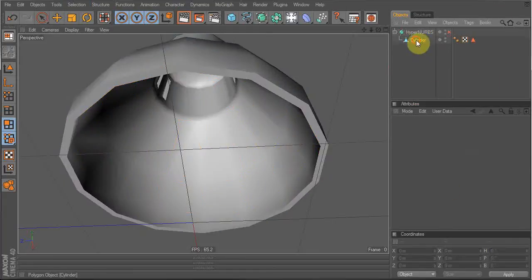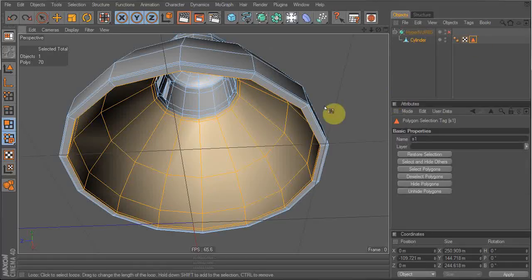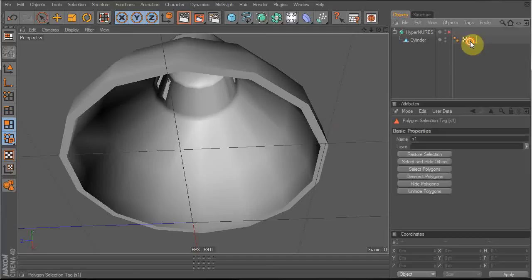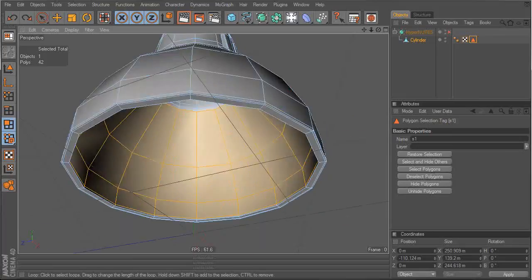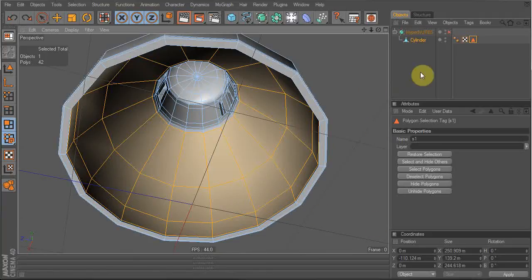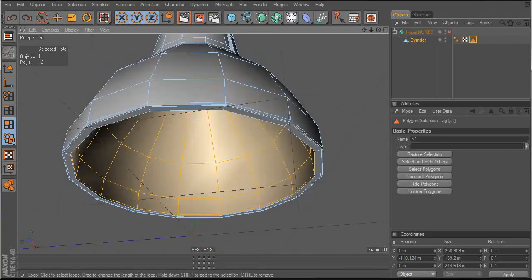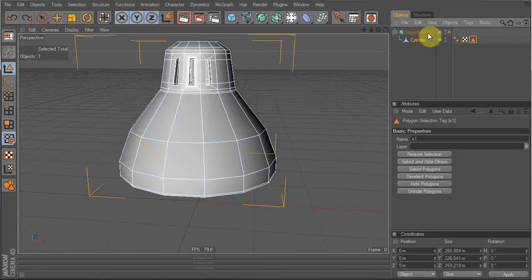Oops, no, sorry. Be careful not to have this thing selected, because otherwise, see what happened, it selects. So we go Control Z before we set selection. Oops. Okay, we seem to have selected. We stuffed up our selection because what I did was, we had this triangle selected when we pressed set selection. Very bad thing to do. So, actually no, we don't need the exterior selection anymore. We only need the interior one, because we're going to be changing the material inside the lamp to what is outside the lamp to make it more reflective. Okay, well, let's keep working.